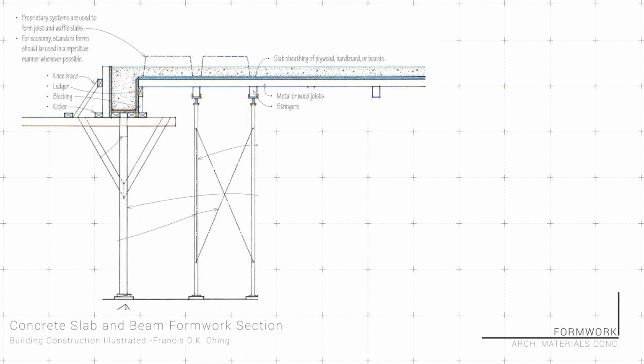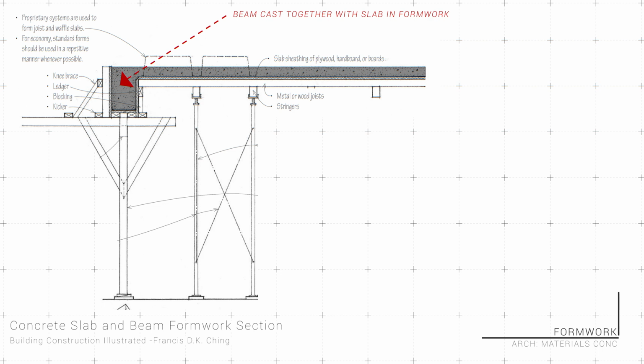Above concrete walls and columns, there is the matter of elevating concrete slabs as they set. Formwork on floors is basic enough, effectively just a shallow tray with a form for beams and one- and two-way systems when needed. Depth here is equal to that of the slab, with extrusions for the beams.